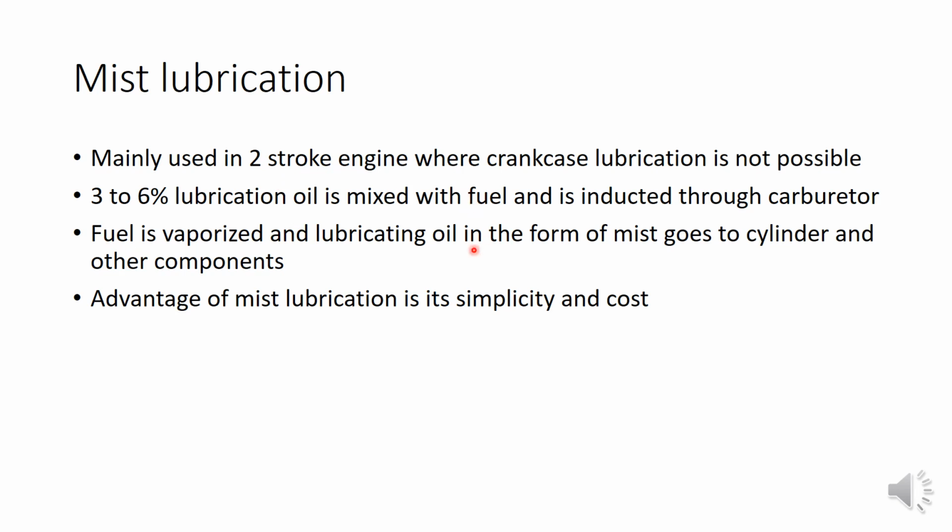So that is mist lubrication. The main advantage is it is very simple and very low cost, because we do not require any additional components for mist lubrication. We are just mixing the lubrication oil with the fuel. But it has several disadvantages.